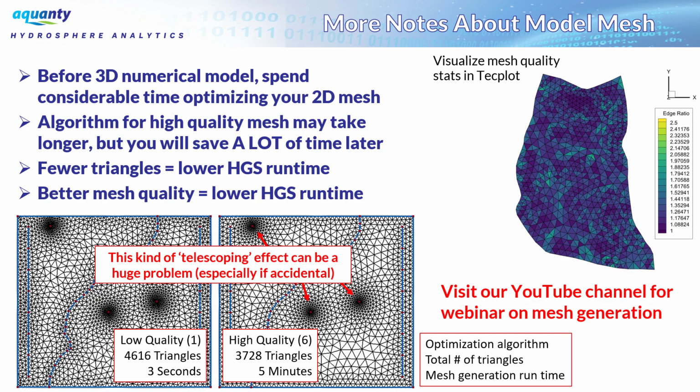This is just a part of the finite element solution methodology and criteria, but in a perfect model, every single triangle within a triangular element mesh would be perfectly equilateral. As you move further and further away from equilateral triangles, you slowly start to introduce numerical instabilities, numerical issues that become harder to solve. So again, a better mesh quality is going to result in lower HydroGeoSphere model runtimes.